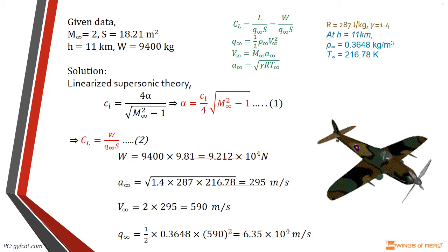We make the assumption that the lift coefficient of the wing, capital C suffix L, is the same as the lift coefficient for the airfoil section making up the wing, small c suffix L. For subsonic flight, we know that such is not the case. For supersonic flight, such is also not the case. For a straight wing in supersonic inviscid flight, however, the wing tip effects are effectively limited to the region inside the Mach cone with its vertex at the tip leading edge.